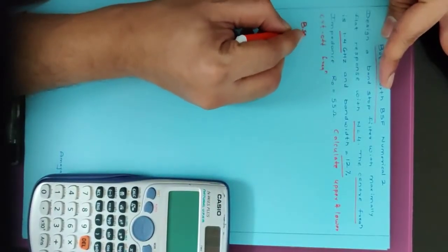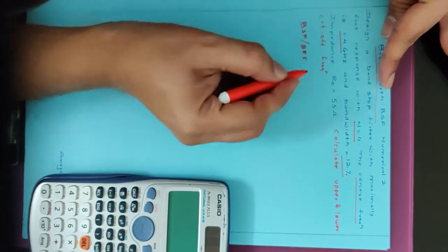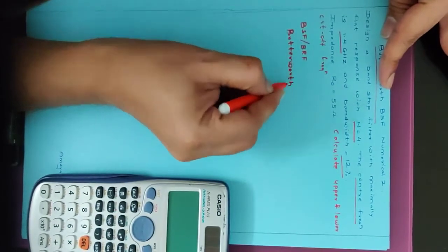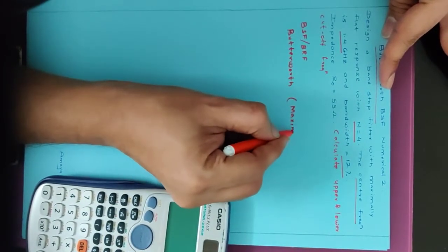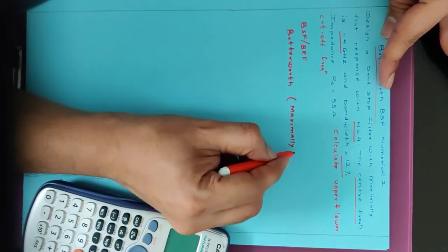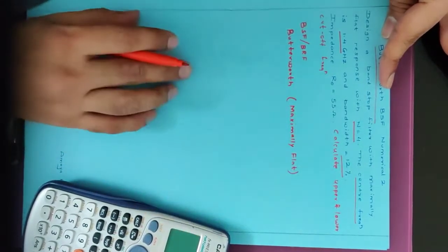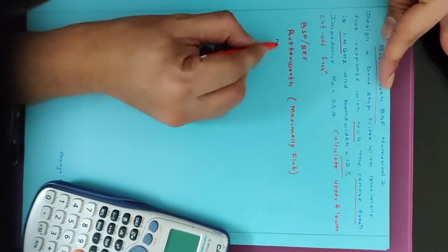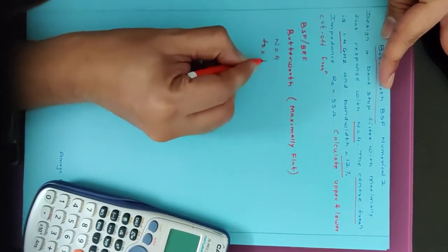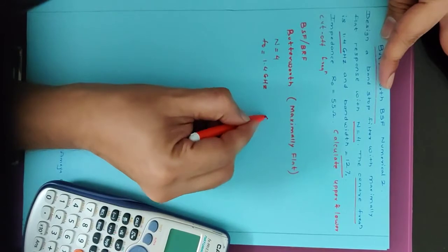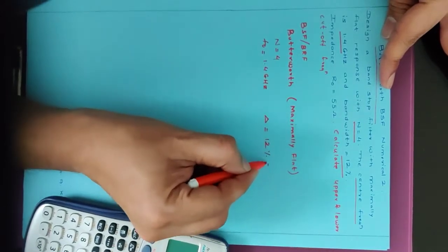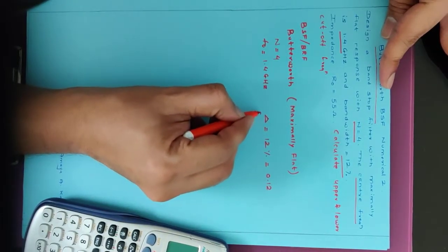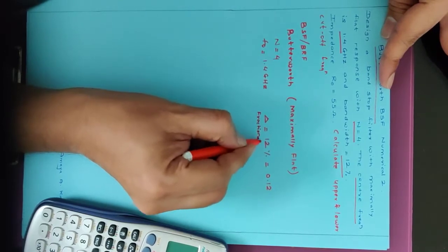So I have to design band stop filter, or you can say band reject filter, for Butterworth response, or you can say maximally flat response. It indicates that there is no ripple in the pass band. Now n is equal to 4, f naught is given as 1.4 GHz and delta as 12%, so delta is 0.12. Delta is nothing but fractional bandwidth.